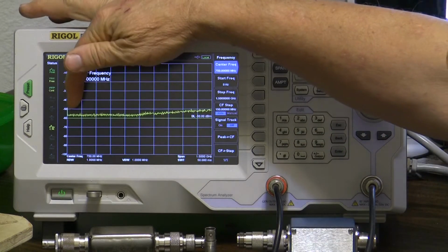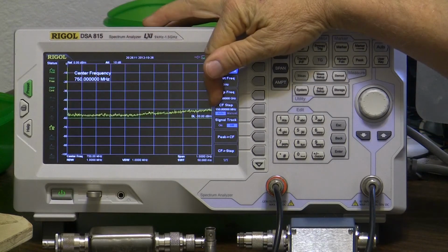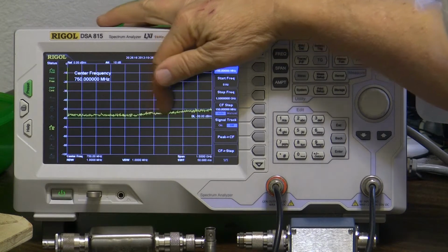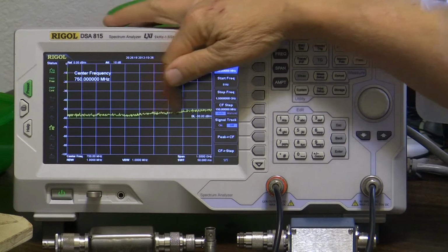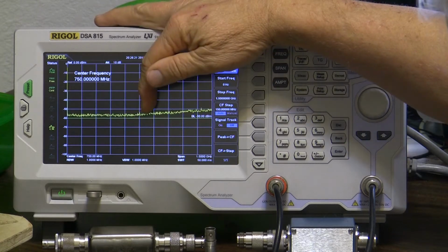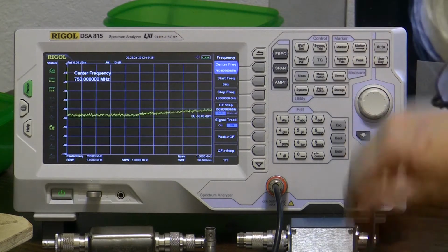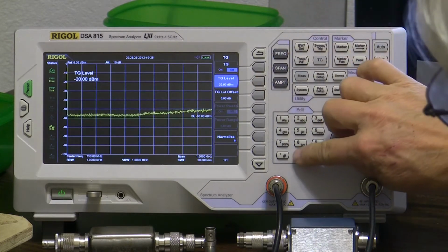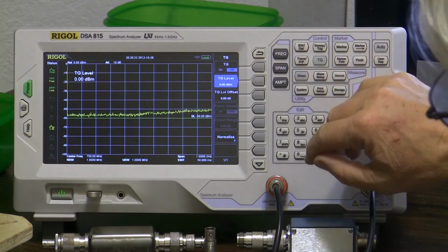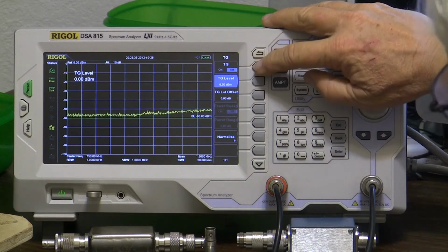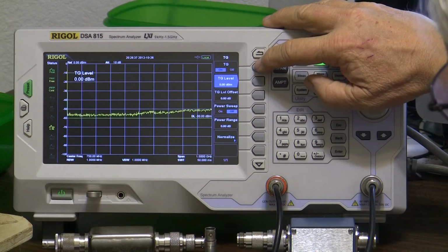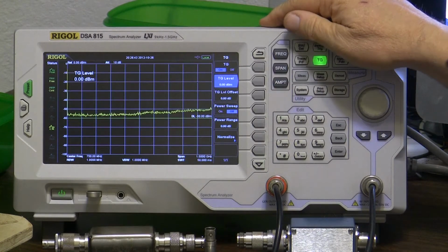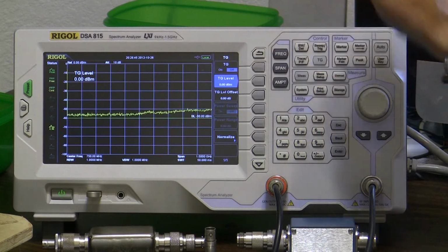As you can see, we're going from 0 to 1500 megahertz, and it starts rising in the 700, 600 region here, and loses about 5 dB of signal to noise by the time it gets up here. If I go to tracking generator, put the level at 0 dBm, and then turn on the tracking generator with this switch, you see that the noise level, even at 1 megahertz bandwidth, rises a little bit. All right, we'll turn it back off.